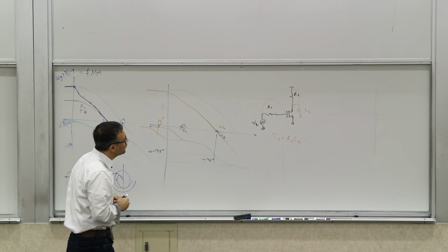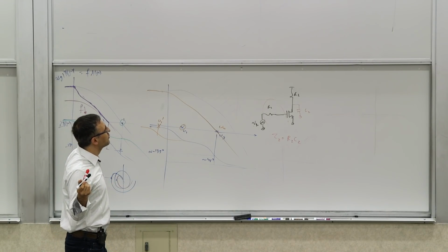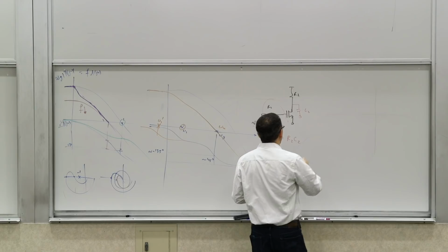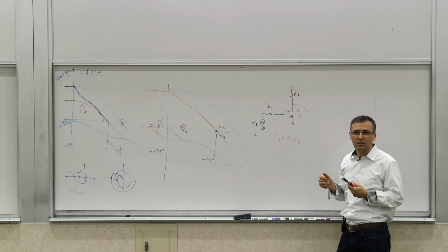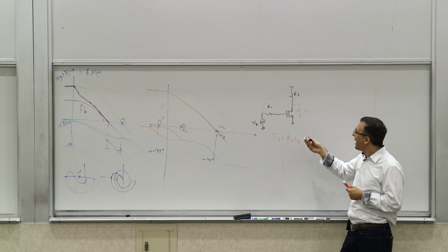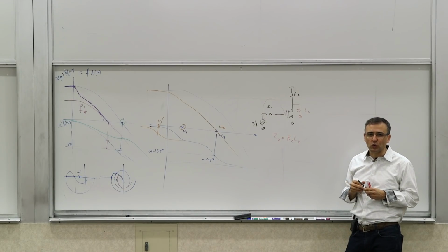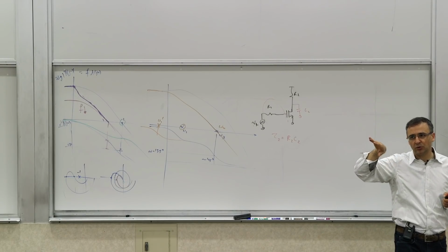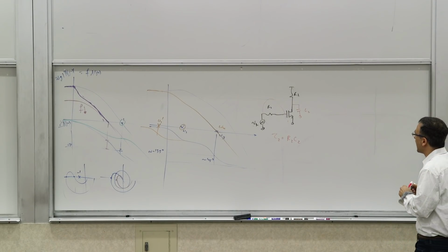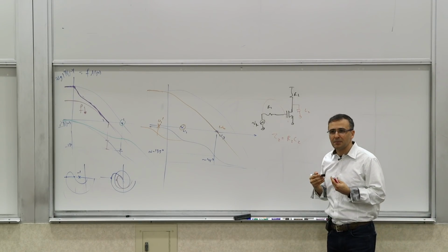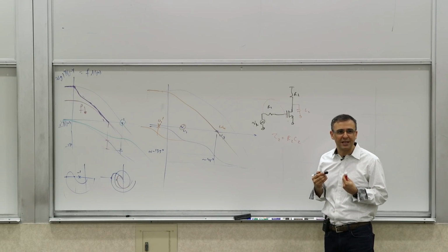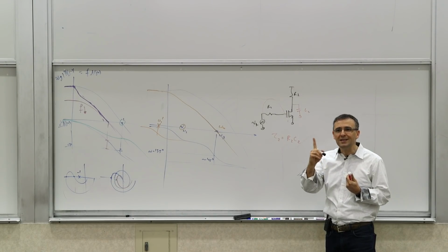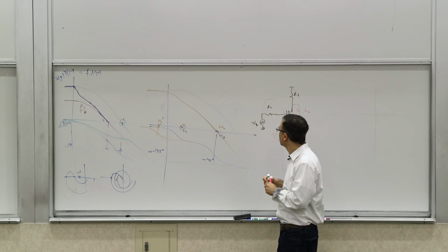Now, if you have an R2C2 time constant at the output, one way to increase it is by increasing C2, right? But what happens if I try to increase it by increasing R2? Let's assume that I can get the biasing and everything right, so you don't have any other reservations. Well, obviously, the time constant will go down, right? But would this change the behavior of the circuit?